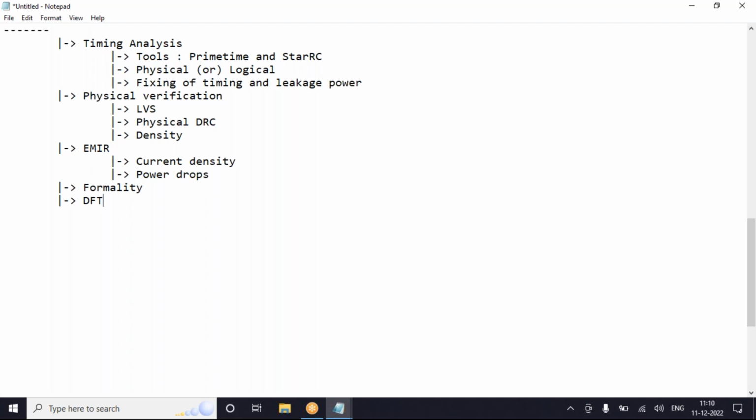I need to verify it is good functionality wise, and there are no changes with respect to the netlist. We are performing some kind of routing, some kind of operation changes, right? During optimization, it doesn't change the functionality of the module, that I need to verify. This formality is a netlist to netlist comparison, and it will be performing pin to pin checks.